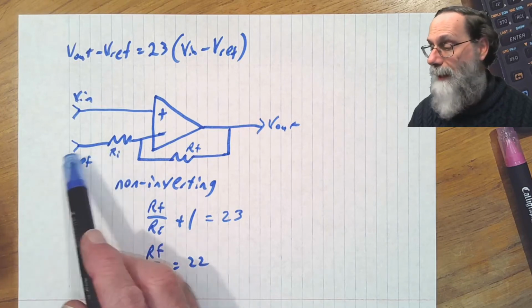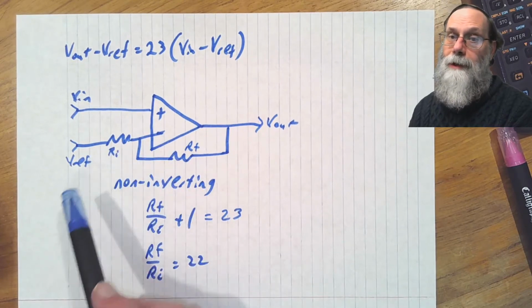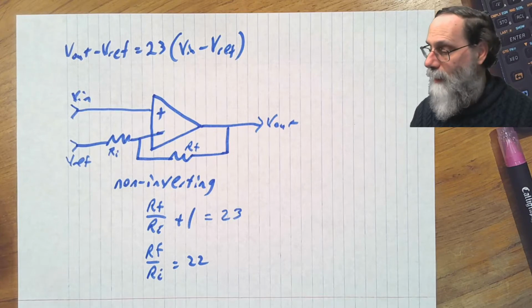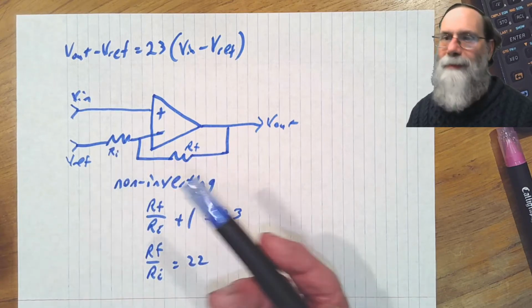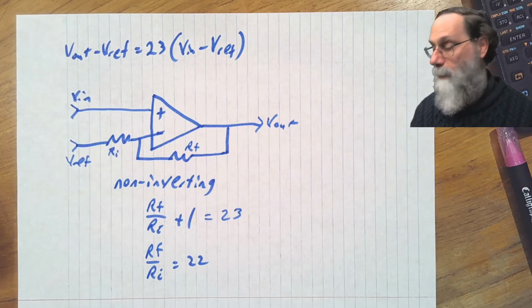We want to have a high input impedance here. We don't want to be taking current from the amplifier to be going to Vref either, so everything's going to be big. We want to be up near the mega ohm, which is sort of our rough rule of thumb as our upper limit.